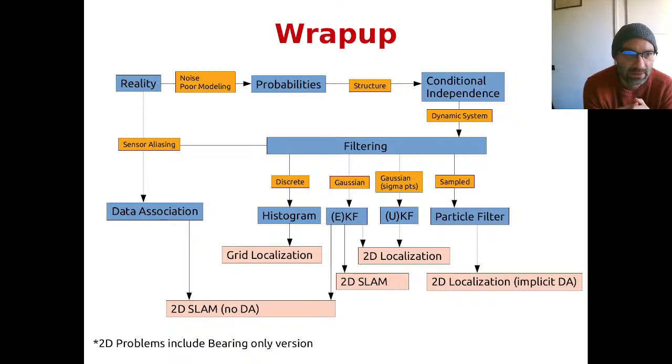One example is, for instance, in the odometry, if we have access to the wheel encoders, we might decide to integrate the odometry, so to evolve to the next state just by using the first order approximation instead of a more complete model that considers more powers of the Taylor expansion. So we might do that, and so we lead to a poorer modeling, right? So in the end, the model that we have is not as accurate as we would like it to be, because we decide to make it simple.